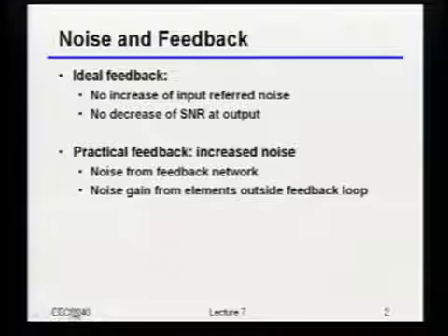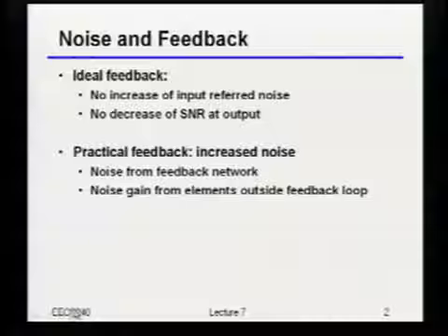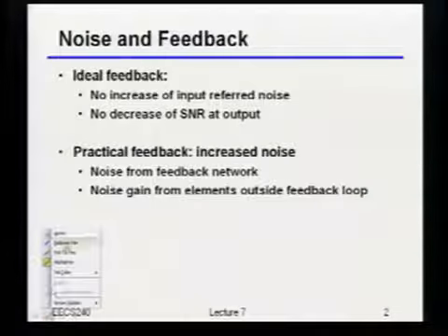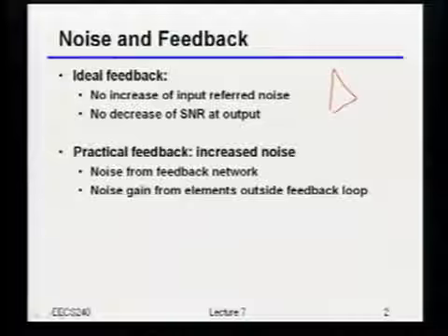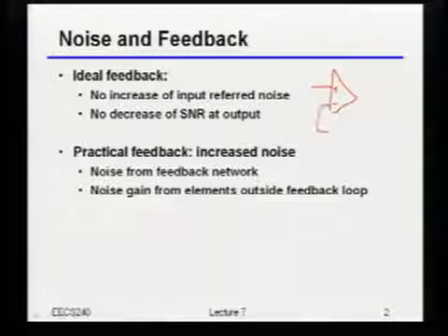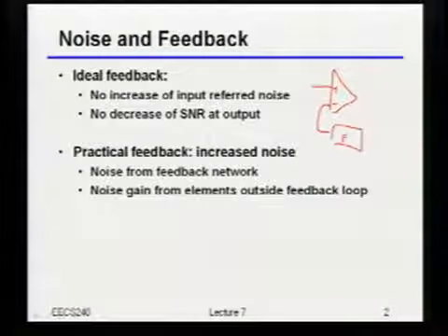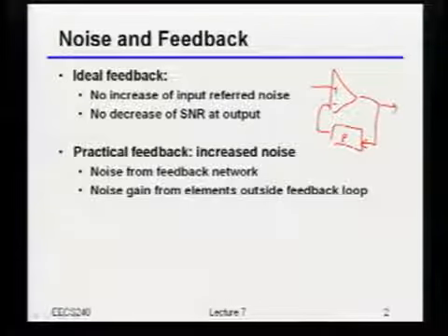If I was a pure linear systems mathematician, then I would claim that taking some amplifier, let's say, and putting it into feedback should not have any impact on the input referred noise. Because if you think about it, let's just draw this. Let's say I have some ideal amplifier, and then there's some ideal feedback gain block like this, right?